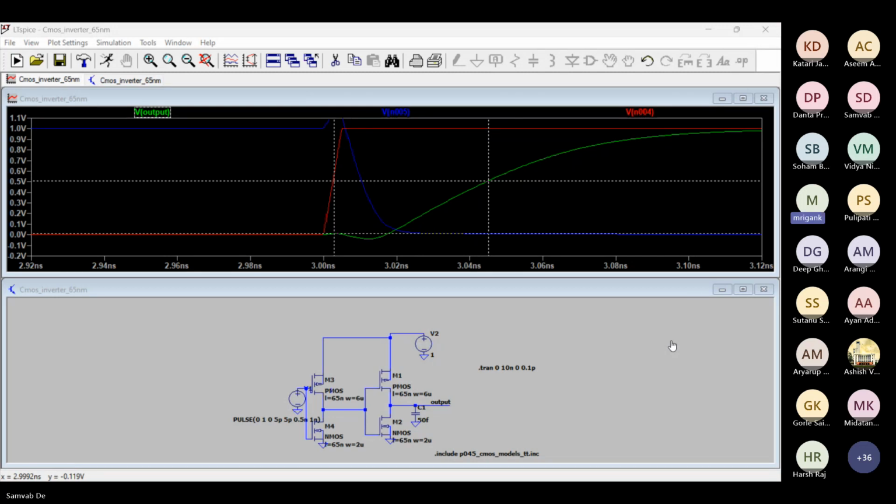The drain to gate capacitance of M3 M4 will also play some role. You can again assume that there's going to be some Miller effect kind of thing between the gate and drain capacitor. The CGD of M3 M4 will play some minor role as well. So these are the capacitances which are contributing to the net or effective load capacitor at the output